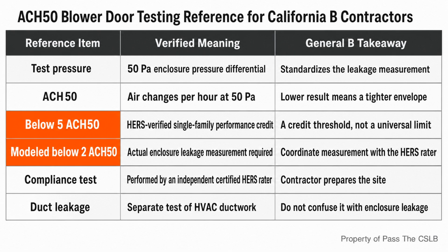The foam installation process also generates heat as the material reacts and cures. Product limits, lift thickness, ventilation, ignition control, restricted access, and re-entry conditions must be handled through the applicable safety information and work plan. I would not invent one universal waiting period for every product and condition.